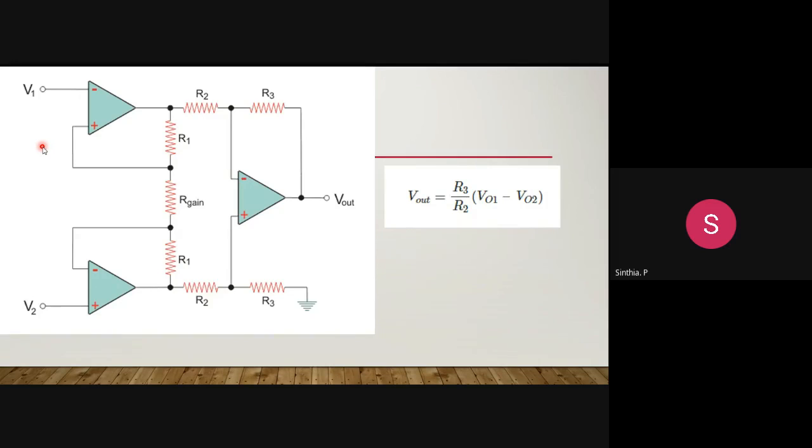Before the signal goes to the next stage, a special amplifier is required, with high CMRR and high input impedance to avoid the loading effects. This high CMRR, high input impedance amplifier is nothing but an instrumentation amplifier. So this will satisfy all the required processes.